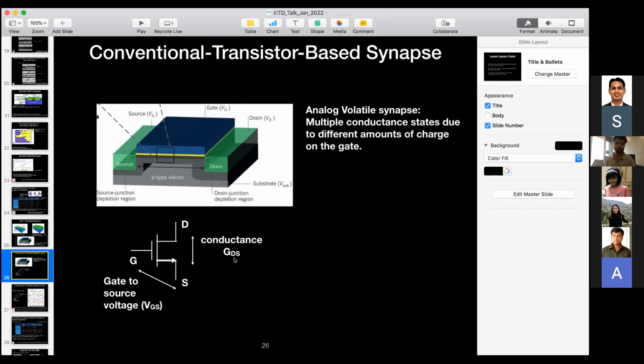So now my question to you is, both are 3-terminal devices. In both cases, you're applying current pulses into the gate and changing the conductance between the other two terminals. But what is the fundamental difference between these two devices? Maybe we can say that in the conventional one, we are using charge as the medium of transport, but in the other one, it was the spin of electrons, the spin orbit. That is the mechanism, but what consequence does it have in the device property?